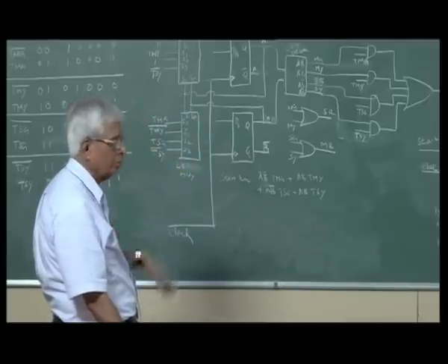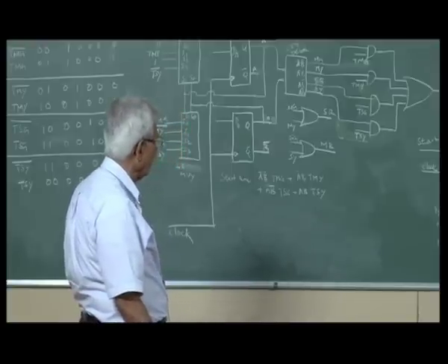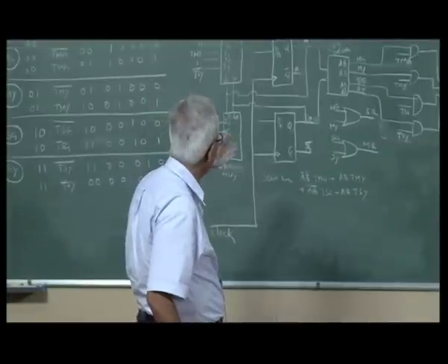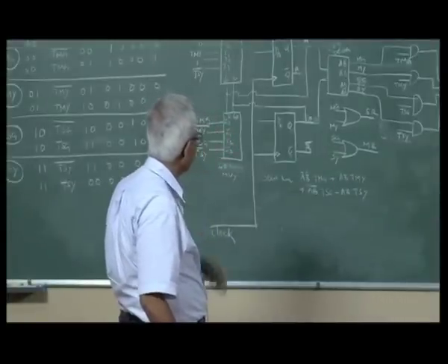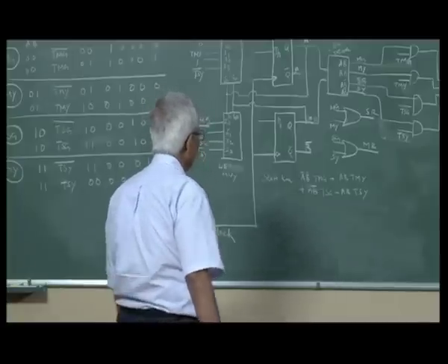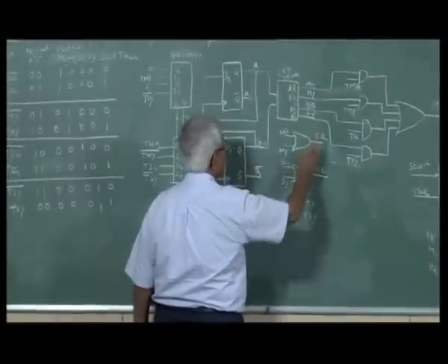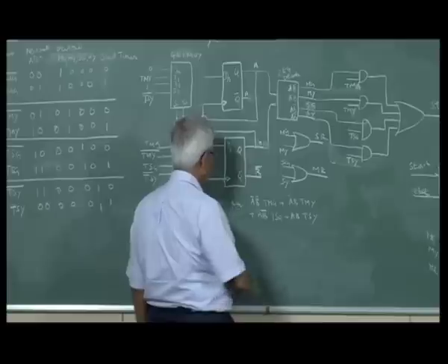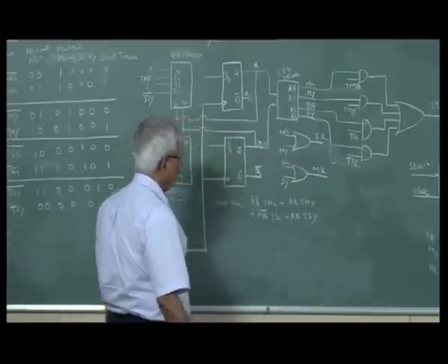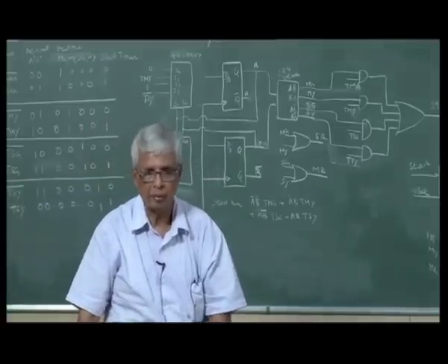Then go to the ASM chart, draw the ASM chart completely, and then translate it into ASM table, and then go to the controller design, and then mark the outputs and combine the outputs in ways required to get the final output. For example, MG and MY to get SR, SG and SY to get MR, and the start timer also goes from these signals and the timing. It's simple. It gives you an overview of a digital system design problem.